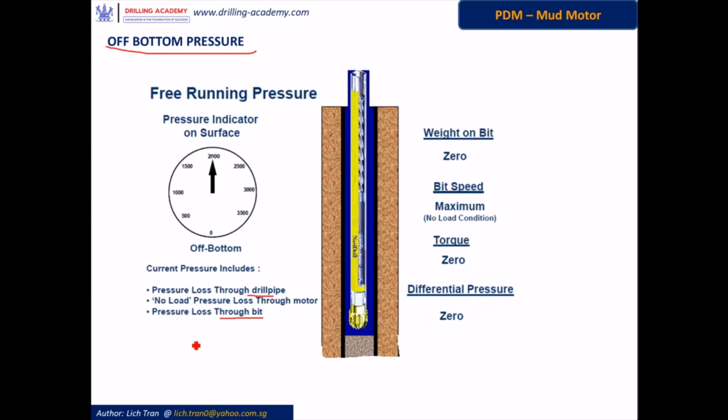And while you are off bottom, you have the no load pressure loss through the motor, meaning the bit is off bottom, no load on the motor. So the weight on bit is 0. The bit speed is free rotating, and let's consider it as the maximum speed at this condition. You have 0 torque from the motor, therefore you have 0 differential pressure while you're off bottom.